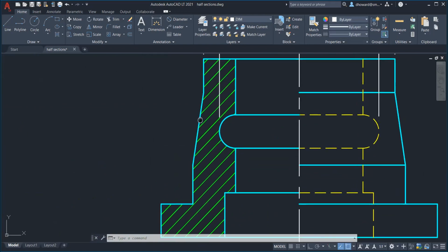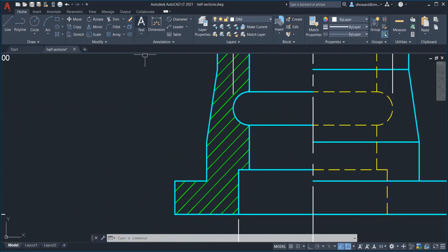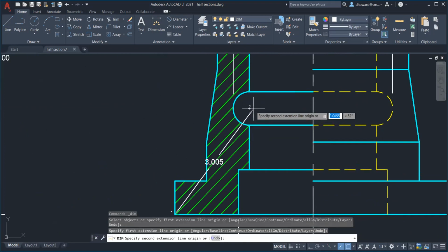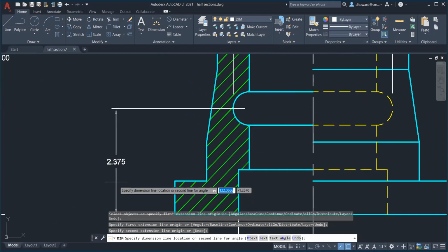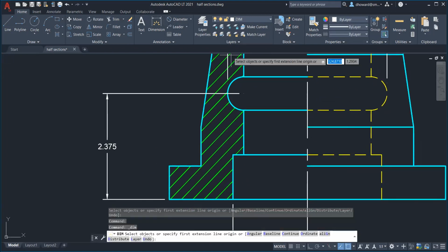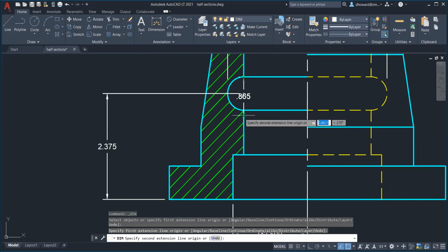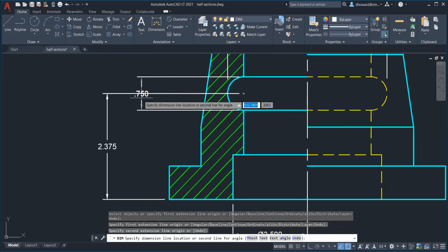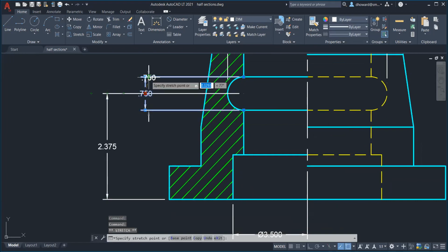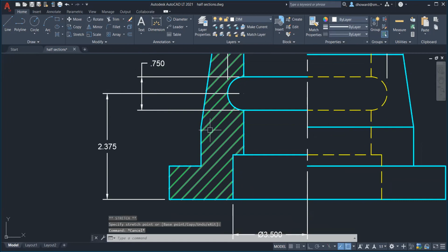So let me show you over here exactly how I did that. So I dimensioned to its center like this, and then I dimensioned its width and pulled that guy out. Now these lines are crossing, and although this is okay, I am not a big fan of that.